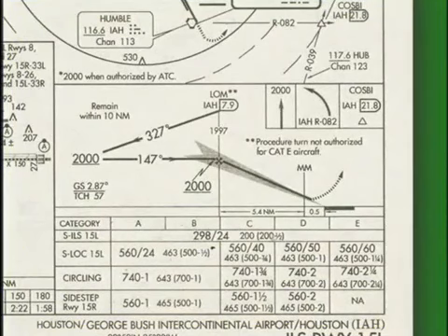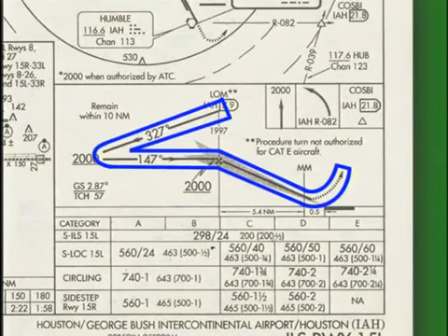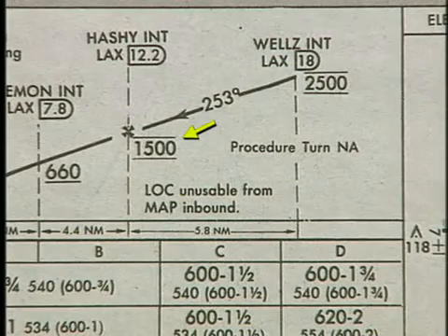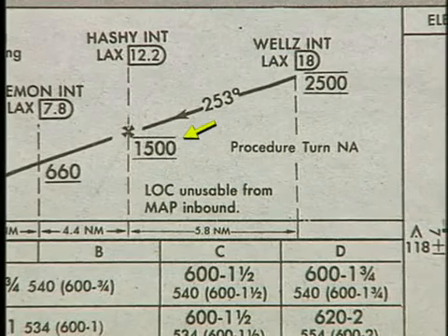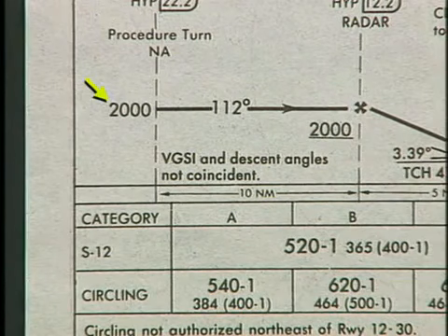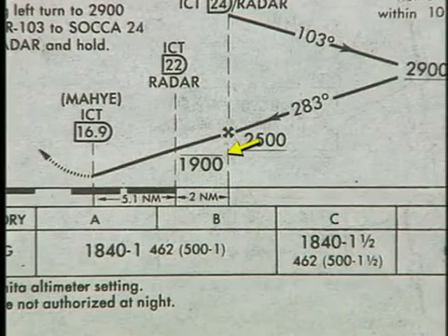This portion of the chart illustrates the approach from the side and depicts the vertical flight path, facilities, and minimum altitudes in feet MSL. Minimum altitudes are shown with a line below the number, while a line above and below the number indicates a mandatory altitude. If the number does not have a line above or below, it is a recommended altitude. Finally, a line above the number indicates a maximum altitude.